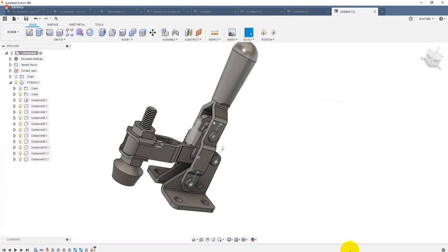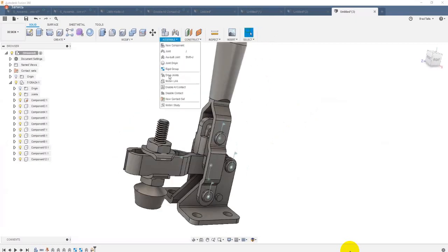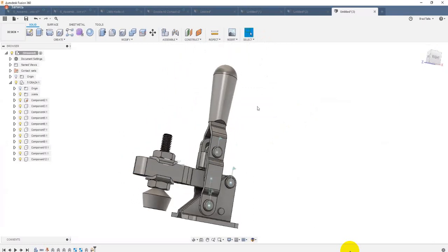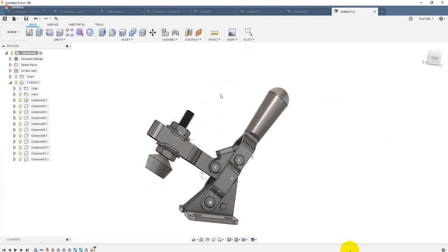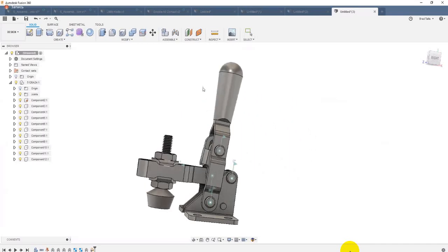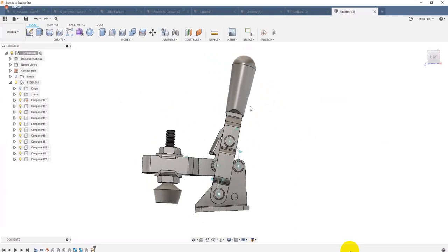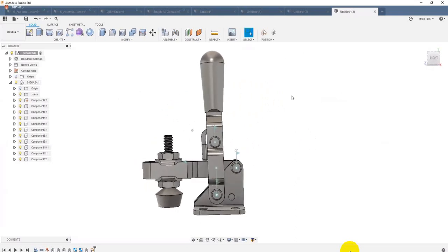This piece here is cutting into that piece there. So I could come in and say, new contact set, that guy and that guy. Say okay. Still rotate to the right and rotate to the left, and I can see I can only go that far. You can kind of see physically won't let it go any further. So cool little trick there.